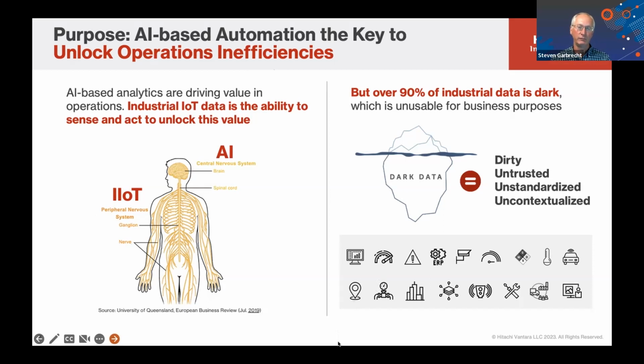You can do retrievals from historians and try to pull it back in all one format. That'll give you at least, from that one historian, a common time reference that it will interpolate data as part of that. You can do further interpolation in the data lake itself when you're setting up data sets for different purposes. So you try to make it as clean as you can at the source, and then you can do some things in the overall repository to make things more accurate too.